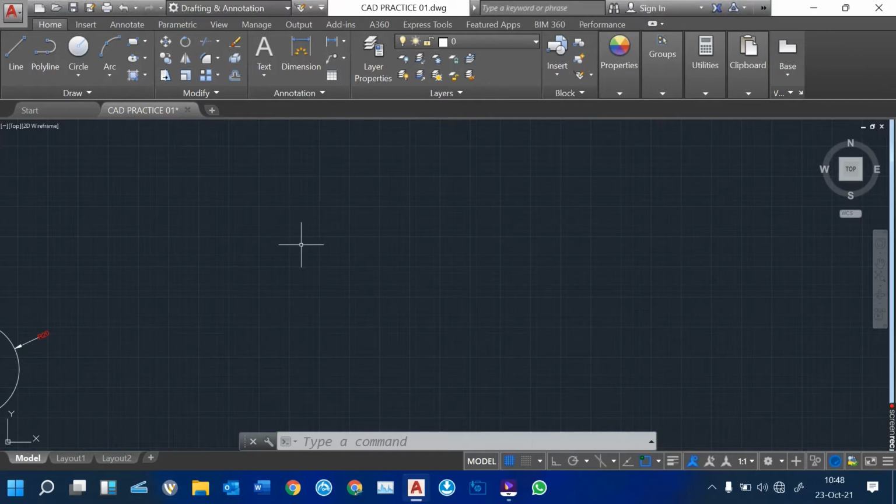Okay, so today I want us to move on to how we can use these modifying tools to modify various objects that we have drawn using AutoCAD. These modifying tools help us to modify a project or a given drawing in AutoCAD. So under modify, we've got these tools here, which I'm going to show you. We have move, how you can move an object, maybe displacement of an object from one point to another. We also have copy. We have mirror. We also have trim and much more.